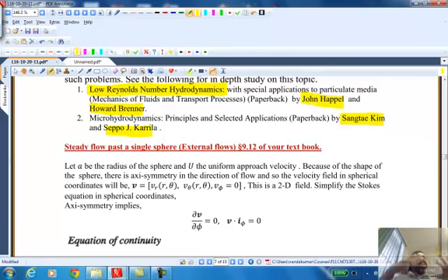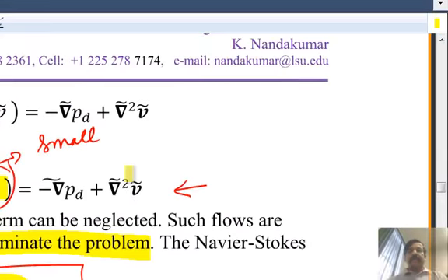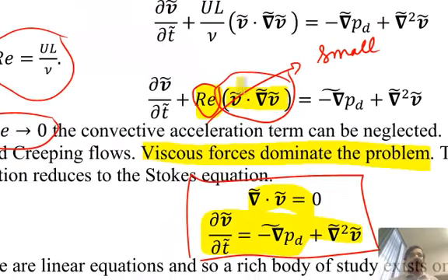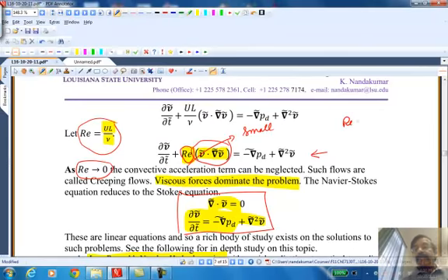That scale analysis is actually valid for three-dimensional flows as well, because we never said anything about the nature of the velocity field. We just took the full Navier-Stokes equation and did a scale analysis on that to show that the inertial term gets multiplied by Re. The physical interpretation of Re is that it is a ratio of inertial force to viscous forces. Why? Because Re is the length times U times rho divided by mu.